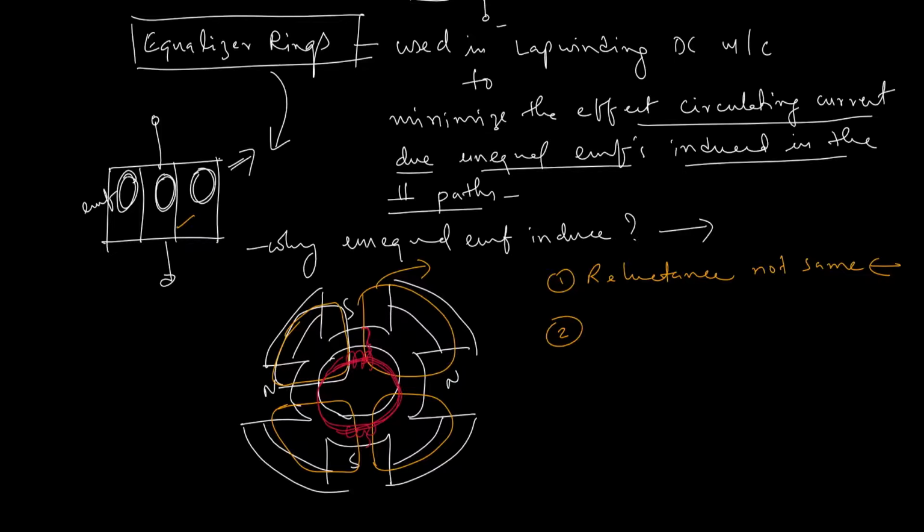That is one cause: aging and wear and tear of bearings may shift the armature and cause unequal EMFs induced in the parallel paths.